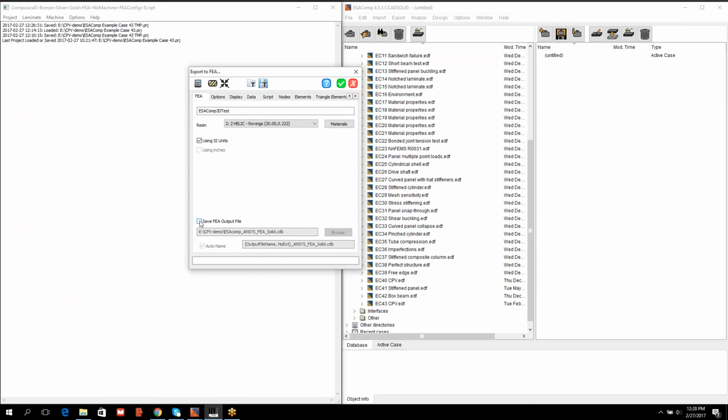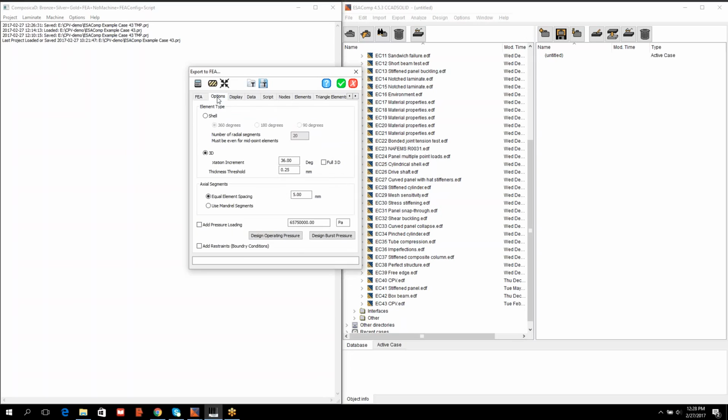One specifies which material is assigned for the resin filler. In this project we have 7 material systems and the last one is selected. Under the Options tab, one sets the parameters for the mesh. The 3D rotation increment could be 2 degrees, for example. Some other small angle can be used as well.